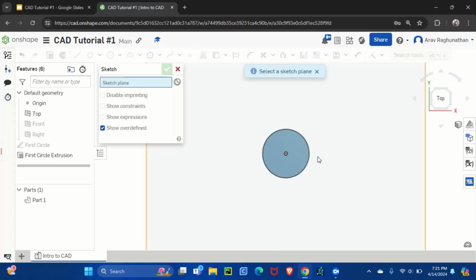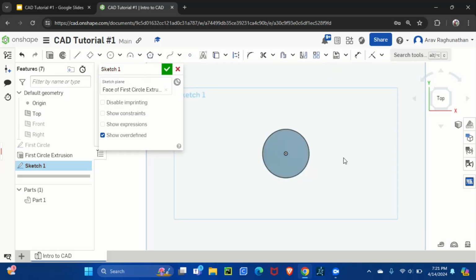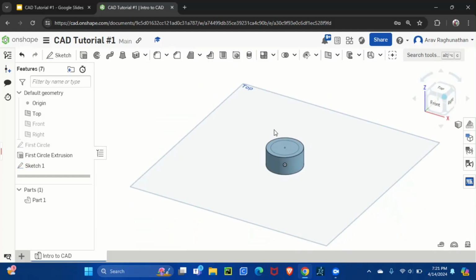All right, so let's go into that. We're going to create a sketch, and we're going to click not the plane but the surface of this first extrusion, so that we can do that pretty easily. We're going to start here. Let's extend out. You can set it to any arbitrary length because we're going to set the length later. Click on dimension, then click on the outside here. I'm going to type in 0.5. Actually, sorry, it was 0.75. So 0.75. There you go. Beautiful.